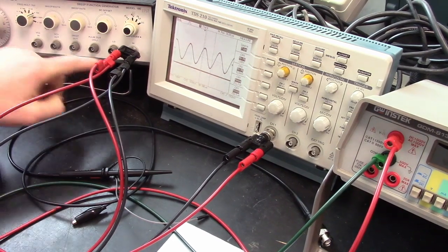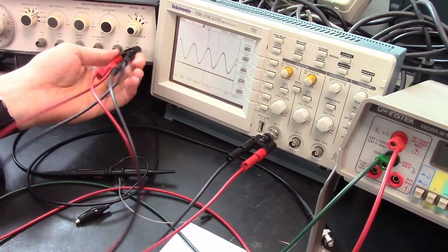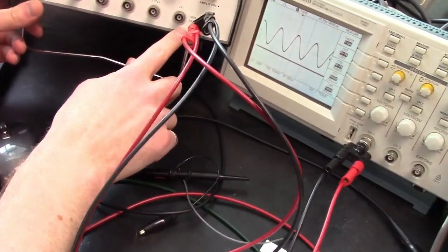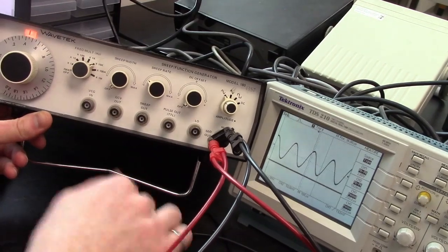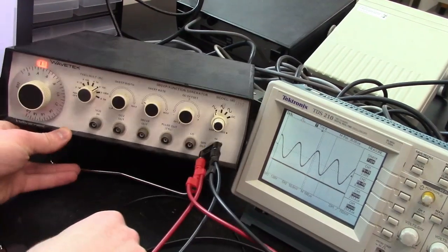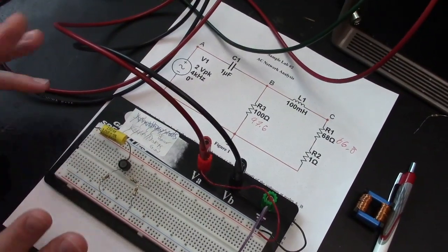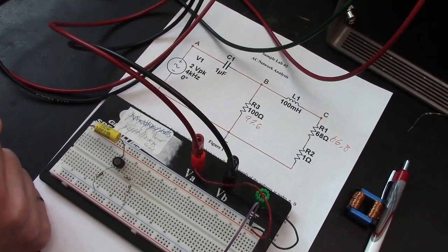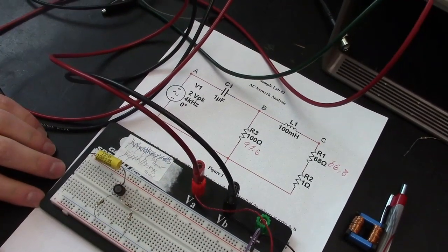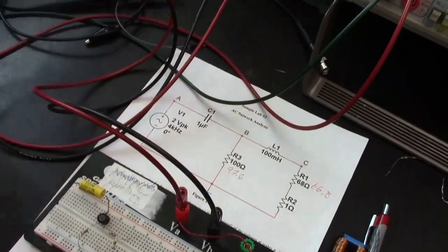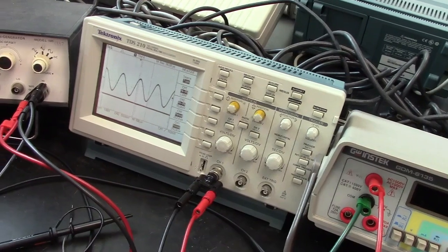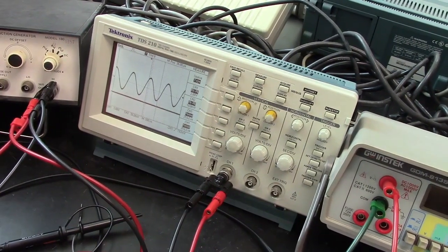And the reason for that is the output of the function generator, if you look really closely, you can see it says 50 ohms out. So that means that the impedance of this device is 50 ohms. And if you put this across this other circuit here, which turns out to have a total impedance comparable to 50 ohms, then we get a voltage divider where not all of the output shows up across the actual circuit. That wasn't the case when we were applying it to the scope, because the scope has an impedance of about 1 megaohm, so it's much higher impedance than the device here.